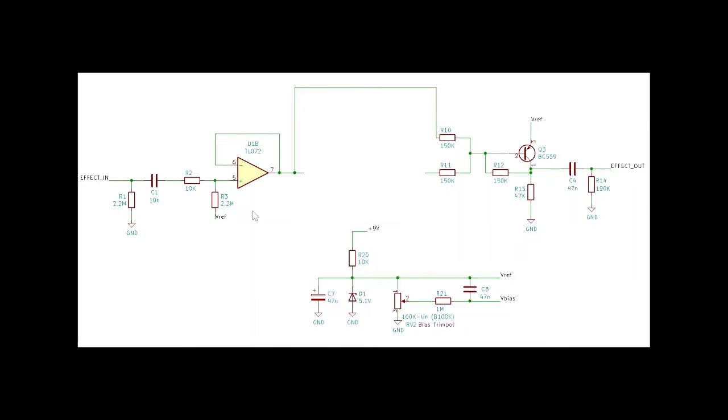First, we have this input stage, and then this output stage, which is also a mixer stage. The input stage we've seen before, standard stuff. I slightly adapted this: I added this resistor, which helps with the popping sound when you switch the pedal on and off.